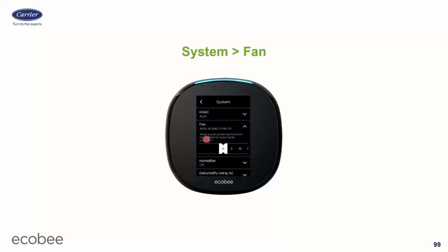I can go in here and make sure the fan runs a certain amount of minutes out of the hour. Now, if you run it all the minutes out of the hour, right, run it continuously, obviously the IAQ devices are going to do better in that case. But maybe you have an old PSC fan and you don't want to pay to run it all that time. So you say, you know what? I'm just going to run it 20 minutes and we're going to call it a day. So this is where you can do that kind of thing.